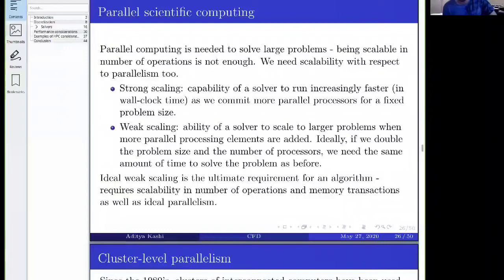For example, we want to capture the boundary layer, so there are these very high aspect ratio cells in the boundary layer. That is one thing. And then for unsteady problems, there is vortex shedding, so we want to be able to capture the shed vortices, and the mesh has to be good enough for that. So there are many different considerations, and I cannot really give a good answer to that.